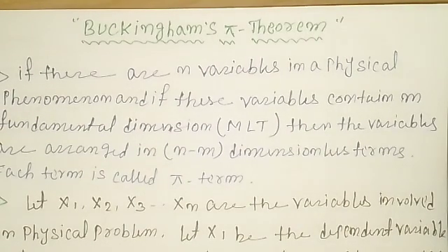As you know, the Buckingham pi theorem is used when the number of variables is more than the fundamental variables, or you can say when the number of variables is more than 3 to 4. Then using Rayleigh's method is quite complex, or somewhat difficult. To overcome that difficulty we have to use the modified form which we call the Buckingham pi theorem.